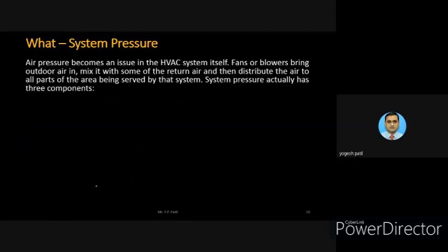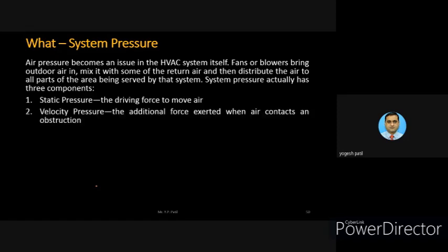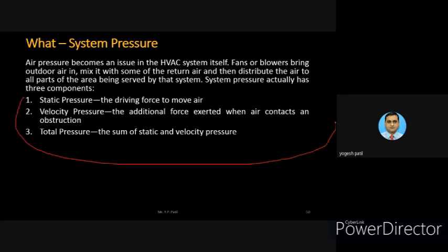System pressure is also there. Not only differential pressure, but system pressure is also required to be considered. In that again, there are static pressure, velocity pressure, and total pressure. So pressure measurement is a very important part of building automation.